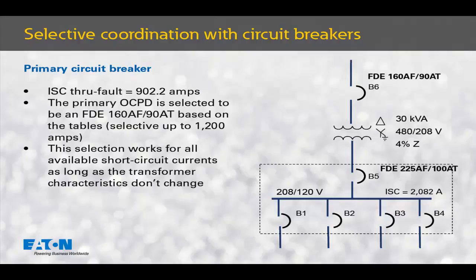If my percent impedance is greater than 4% in the as-built phase, I may be able to select different circuit breakers around this transformer as the short circuit currents will be lower, and I may be able to use smaller circuit breakers or devices that are thermomagnetic only without the electronic trip units.